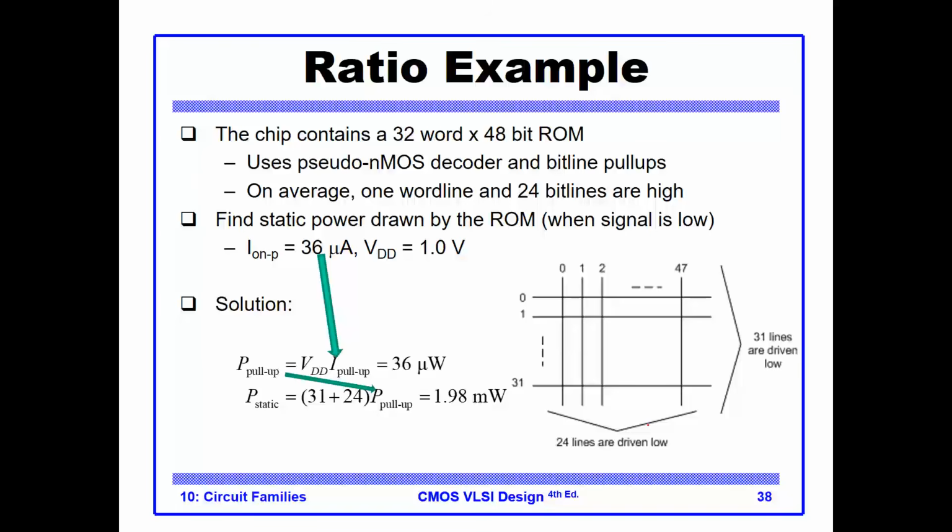Okay, here's an example that says that whenever we have a short circuit, and basically because you will have the current running through the PMOS and the NMOS, whenever this NMOS is on, you will burn basically around a current of 36 milliamp when you are using VDD of 1 volt.